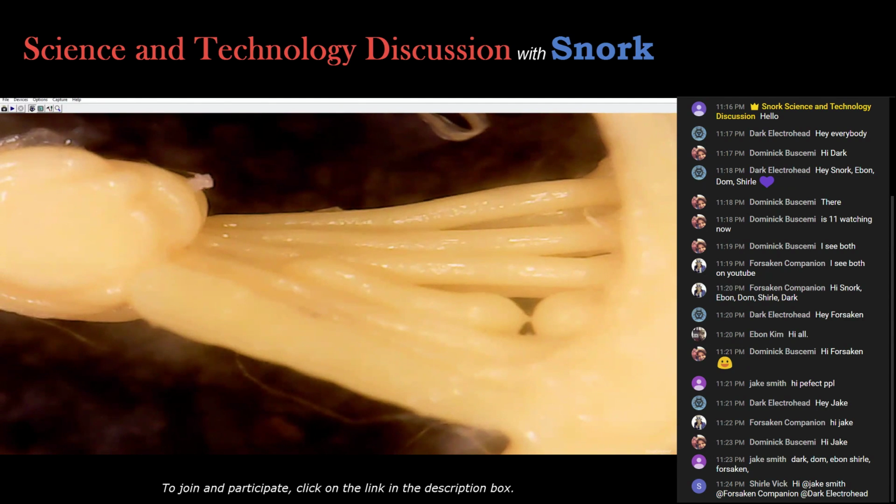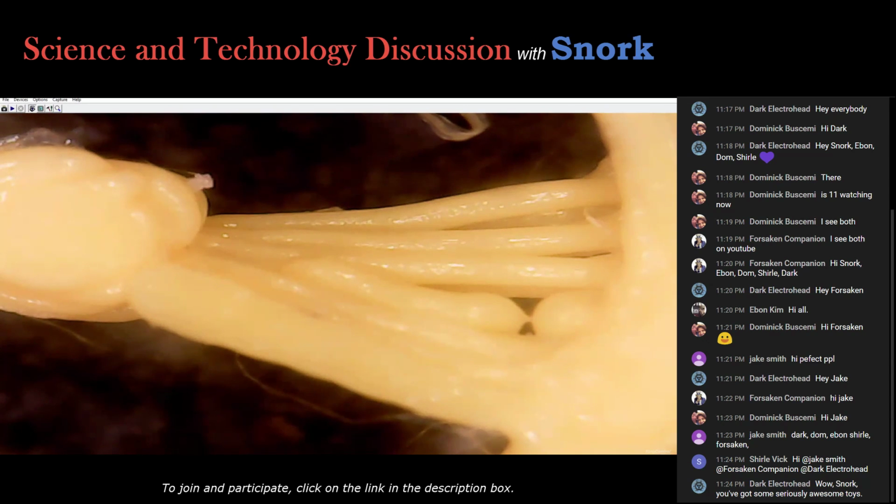sample fan blades, looking at them this close. You can see, and this was one I was playing with to see what pressures and what speeds I needed to move to do these fills. You can actually see where they weren't spaced close enough and didn't have the material flowing at the right rate to completely fill out that fan. So what happens is it prints layer by layer and puts down the plastic in the positions where it should melt together. And that's how it makes a 3D print.